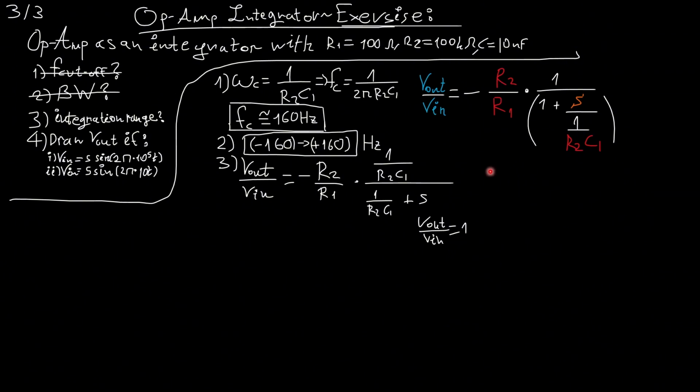If you remember from earlier, the output has a constant value and then it gets lower and lower and lower up until it goes to 1. From there onwards, the output over the input will be lower than 1, smaller. So the output will no longer be amplified from that point onwards. So that's why I will say that this is the final point at the frequency domain that we have an integration. The frequency now must be much, much higher than the cutoff frequency.